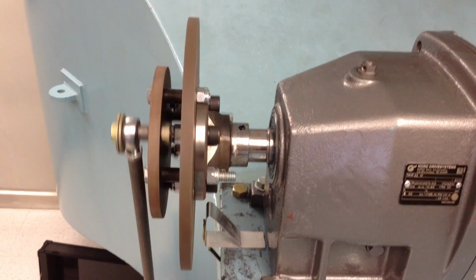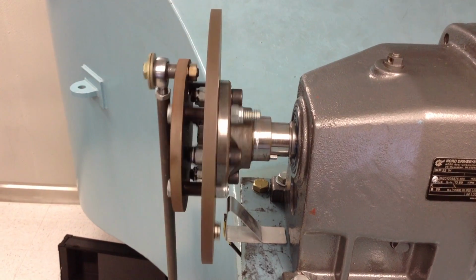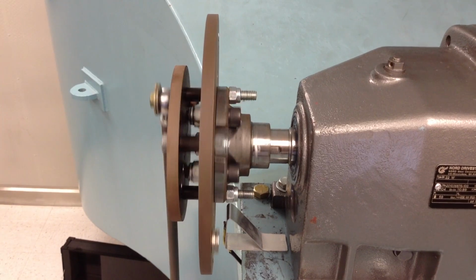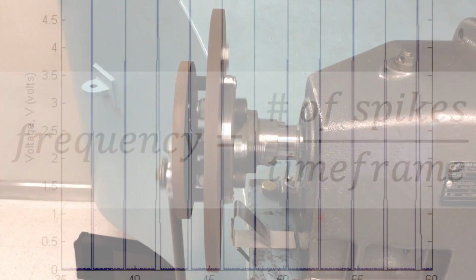A data acquisition system recorded when the switch was on and when it was off. Therefore, it is directly related to the motor's frequency of rotation. This is done by focusing on the data collected for 1 second of the time history plot and counting the number of spikes during this duration. The number of spikes will reveal the motor's frequency of rotation in revolutions per second.